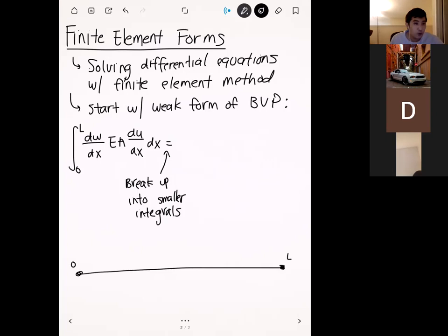If you remember, when we do finite element problems, a big part of it is breaking up or discretizing this domain into a bunch of elements. That's what we do in the meshing step. So instead of working with this big line, let me break it up into all of these small elements, and then I'll label all the nodes x1, x2, x3, x4, x5, x6. These denote the nodes in your finite element mesh that you would produce in a software.